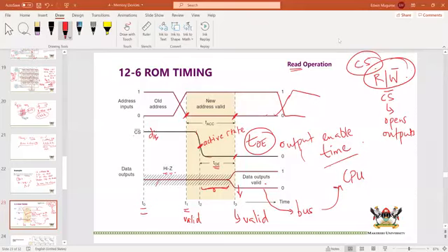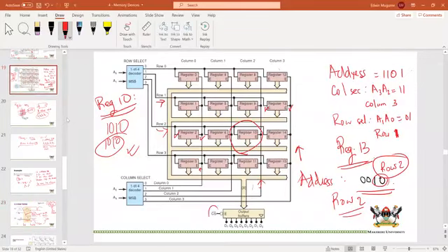The delay is normal. It's just that if you give the chip select, that signaling has to be transferred to the output to cause a change. All of these things take some time. Output enable time. Once again, it is the time between you giving the chip select command, because the chip select command is the one that enables the output buffers. You remember when we were looking at it here, this chip select was high, but now it goes low. It goes low from the point it reaches its midway.